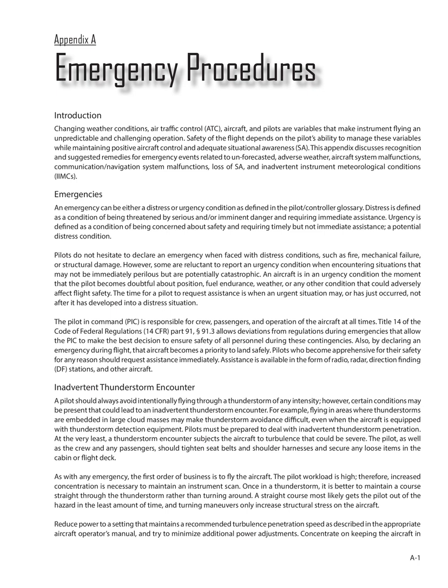An aircraft is in an urgency condition the moment that the pilot becomes doubtful about position, fuel endurance, weather, or any other condition that could adversely affect flight safety. The time for a pilot to request assistance is when an urgent situation may, or has just occurred, not after it has developed into a distress situation.